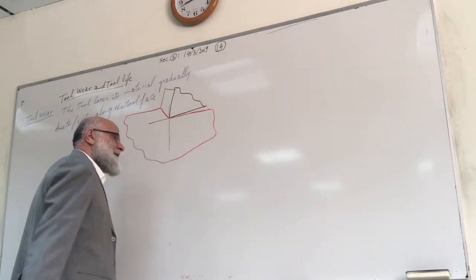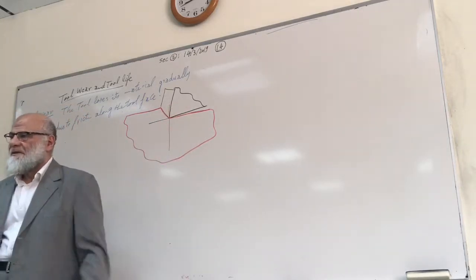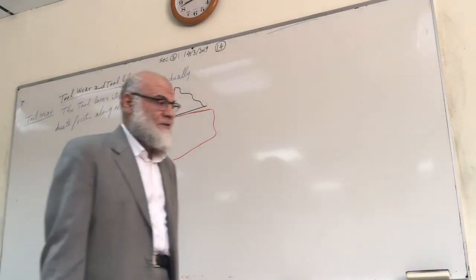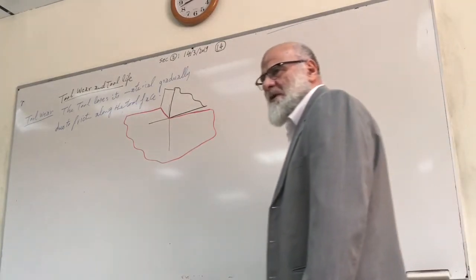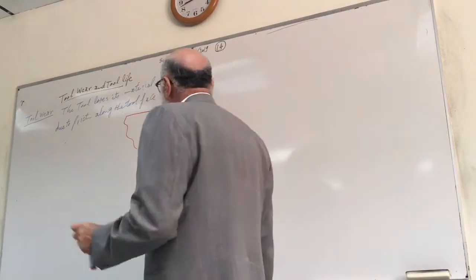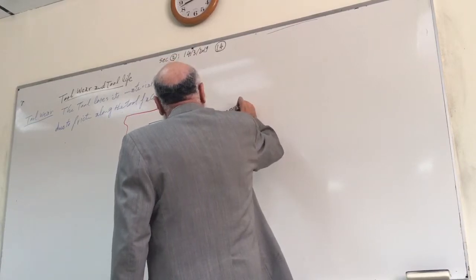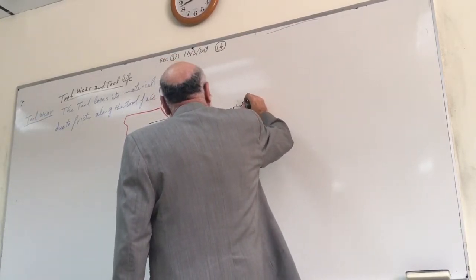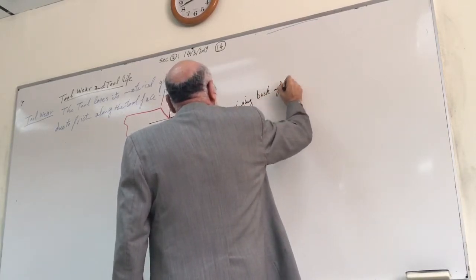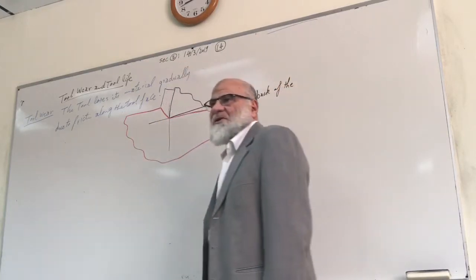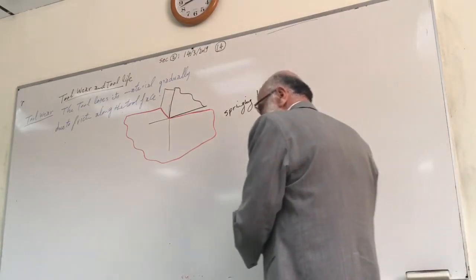Therefore, why do we say that at the first touch between the tool and the workpiece there is no touch? We said previously that there is no touch between the workpiece and the tool, but this was wrong, it was with a certain approximation. In fact, there is what is called springing back of the material. We mentioned that there is no touch between tool and workpiece, and now we say that at the first touch of the tool and workpiece, a fracture or rupture happens at first.